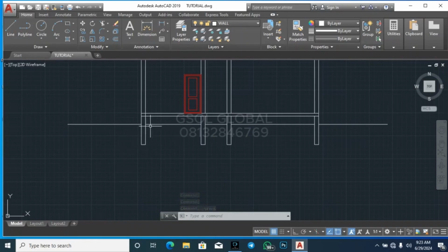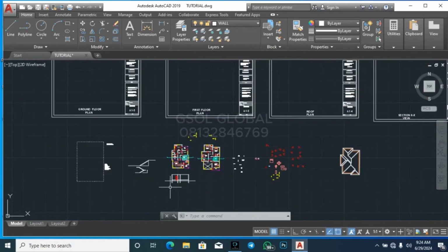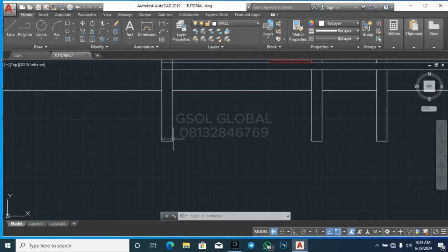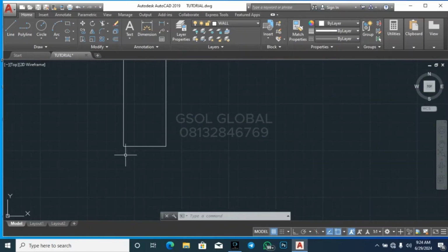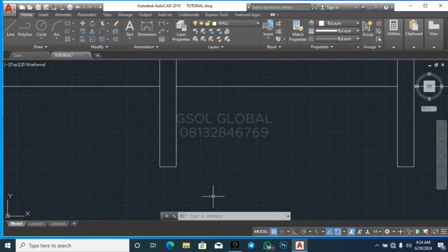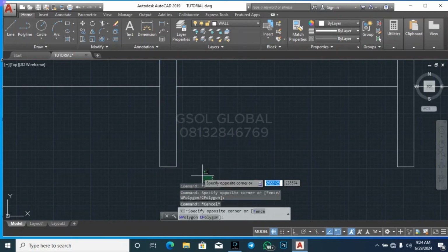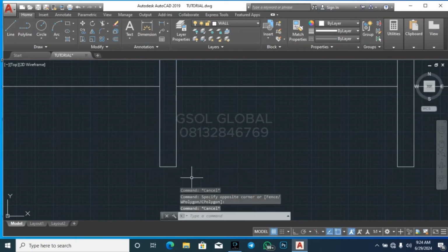All right, what did I say? You go ahead and start doing what? Placing your footings. Okay, so for this one, remember I told you guys that 3 times your wall is what you'll be having as your strip or your footing. Most of the time, this is a duplex, all right? So by analysis, you'll be having this wall is riding on a strip. This is not a column, this is a wall. So this wall will be having a strip of 3 times the wall.